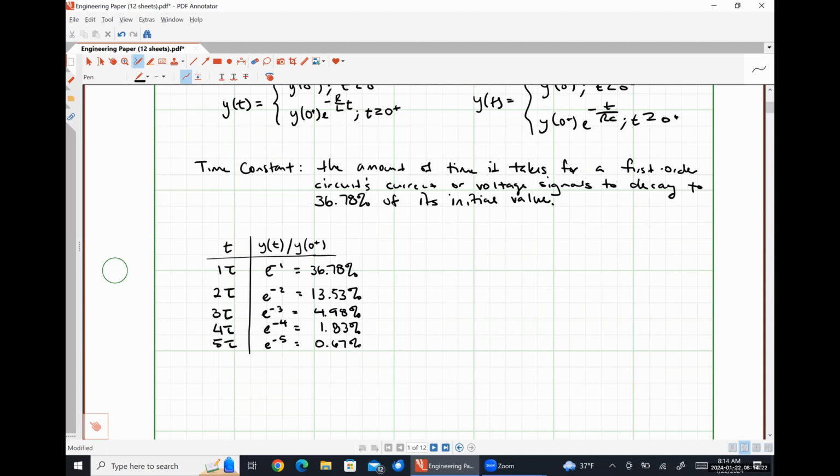So the reason why I'm mentioning this is because we talked about the concept of t equals infinity being a long time after our transient signal has died out. Well, for the intents and purposes of engineers, infinity is just 5 time constants. If we allow something to discharge to where it's less than 1% of its original value, we say that it's effectively fully discharged. So infinity, from the perspective of these transient analysis problems, really just means anytime more than 5 time constants, we're back at a DC steady state. And we'll use that if we have a chance to do the lab for this material.